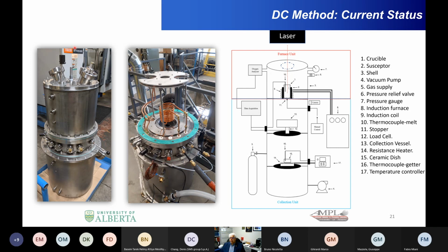the melt. This laser will give us a direct measure of the height of the liquid in the crucible as it flows out. Up to this point, we've been getting the height by calibrating the crucible ahead of time and, after we get the weight of material that goes on the load cell, back calculating where the height was in the crucible.